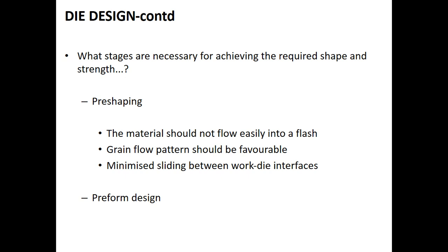And nowadays the CAD techniques, computer aided design techniques, are available to predict the material flow pattern in the die cavity and to predict the formation of defects. The proper preform design assures the defect free flow, complete filling of the die, and minimum loss in flash.